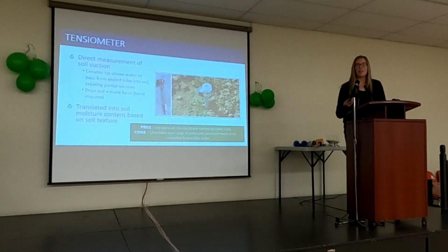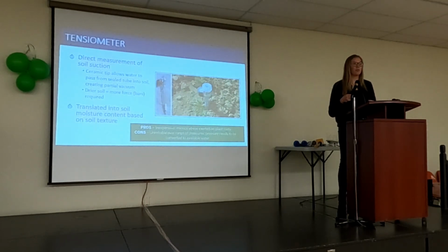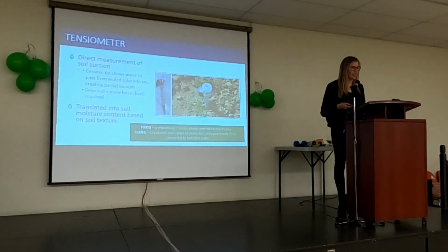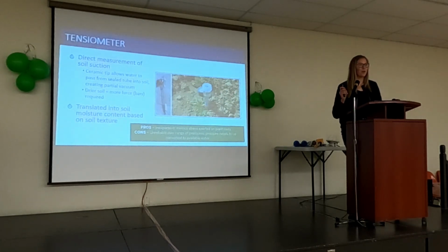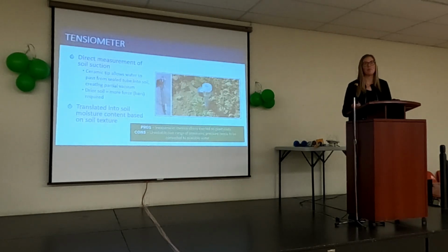So the probes themselves are pretty inexpensive. I was looking online, you can get that one for about $50. So it's not a huge investment, and the technology itself is going to mimic the suction pressure of plant roots, so that's a really great proxy for plant available water, so really nothing wrong with this technology. However, they are unreliable over a range of pressures, but without getting too far into that, if you're working with soils that have a really high moisture content, or else really coarse soils, this probably isn't the right instrument to be using to measure soil moisture.